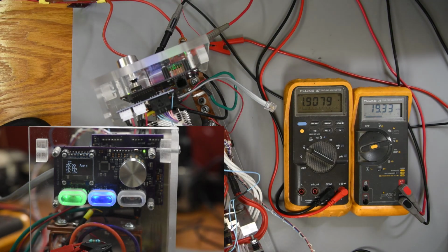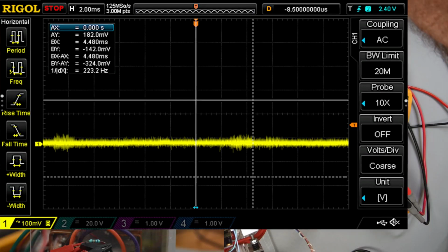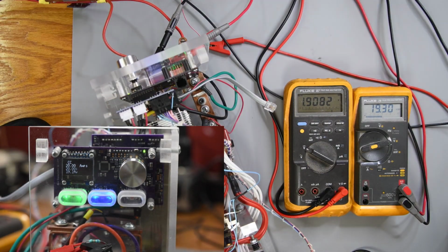Here's the current waveform at the load terminals. The fact that I'm not getting any oscillations makes me very happy. And this supply voltage has a very large 120 cycle ripple on it as well, and I don't even see that in the current waveform. Very pleased with that. I'm going to consider constant current mode working, with some tweaks here or there in the future.